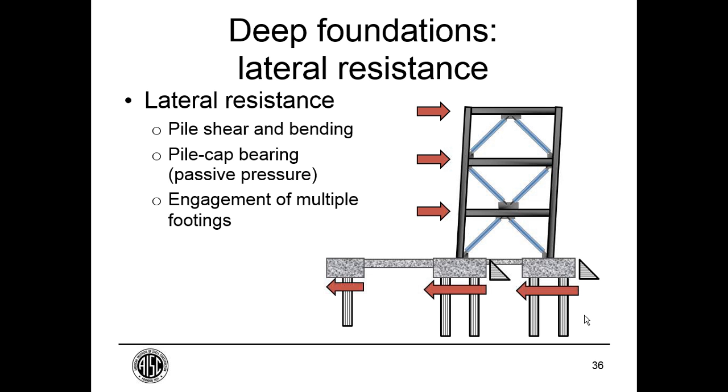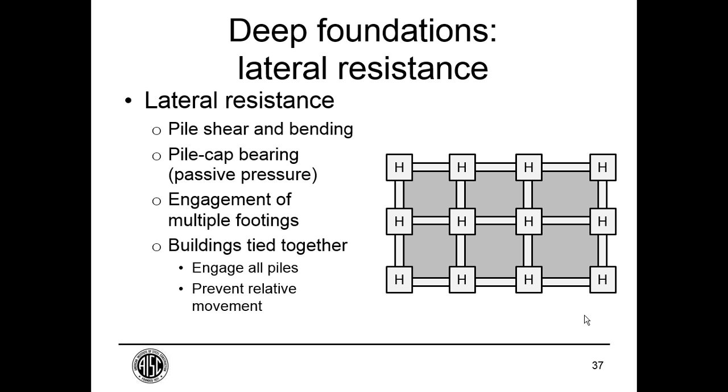If, for design purposes, we run into trouble with insufficient resistance, we can reach out and grab other piles and piers and create a sort of ground floor diaphragm to engage all the piles under a building. That's not uncommon for buildings in bay mud in San Francisco to utilize every single pile. And in some areas, batter piles are common for resisting some lateral forces. And here's a system of grade beams reaching out and grabbing multiple piles.